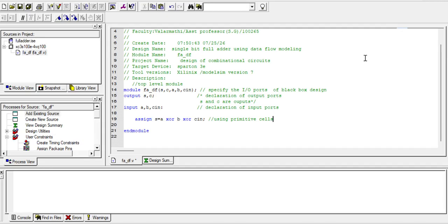So what are the IC fabrication steps? Thousands of steps will be repeated before taking the tape out, starting from substrate, epitaxy, diffusion, oxidation, photoresist, lithography, ion implantation, making metal contacts, with trillions of billions of gates inside the IC. For that, the cooling system and water source management are very important. So that is one of the reasons they have started the fab in Assam.